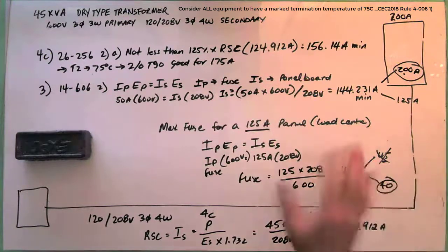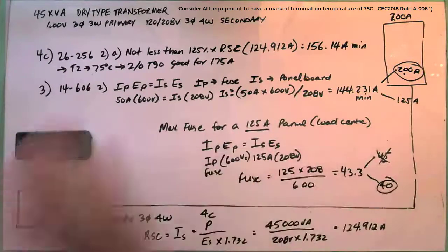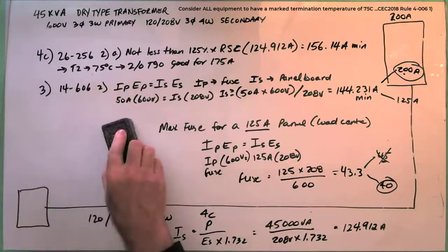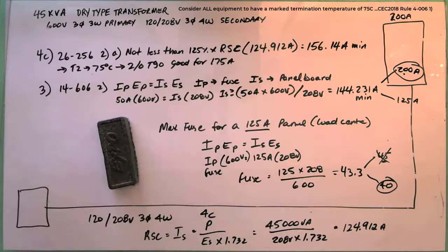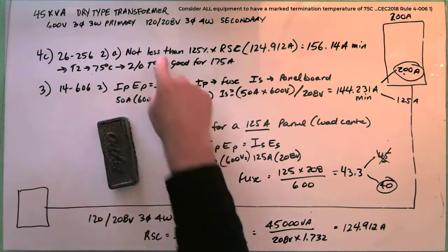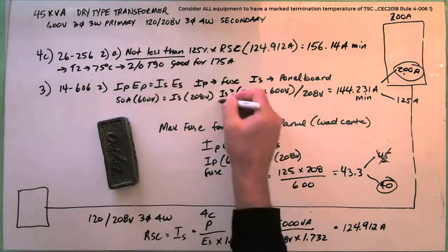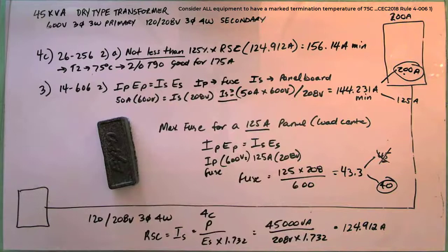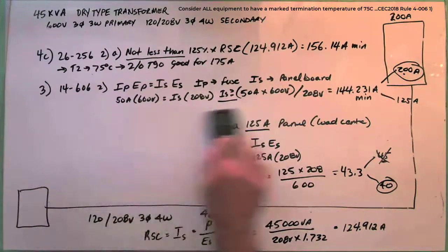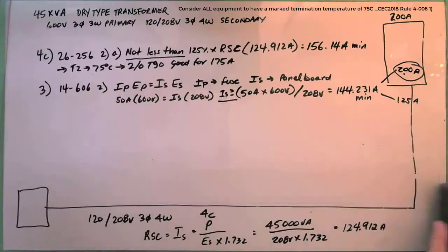You're going to see this again. I'm doing all this because it's going to make your life easier next week. I'm going to erase this. Yeah, so that's what you've got to watch out for. But the code says it. Not less than. The panel board must be greater than. You don't have to memorize the code because it says it. There's no way I'd be able to memorize it. Mins and max, mins and max. So my minimum panel would be a 200 amp.